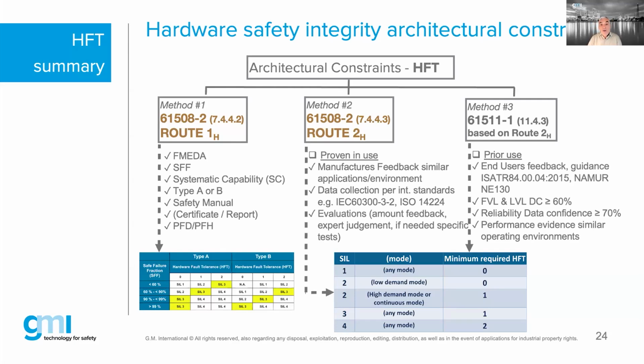So you have to degrade from a safety point of view. If you have a 2 out of 2 before, you need to degrade this into a 1 out of 1. That means the other healthy sensor, if this sensor is asking you to trip, you will trip. There is no other vote possible. Same when you have a 2 out of 3 and you need to calibrate, or there's one sensor in failure, then you need to degrade this 2 out of 3 into a 1 out of 2.